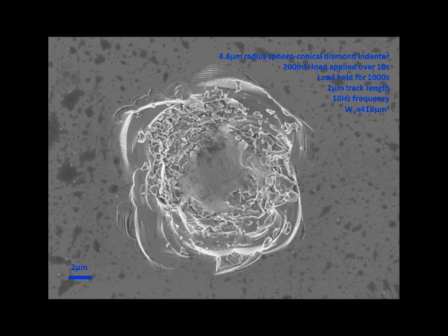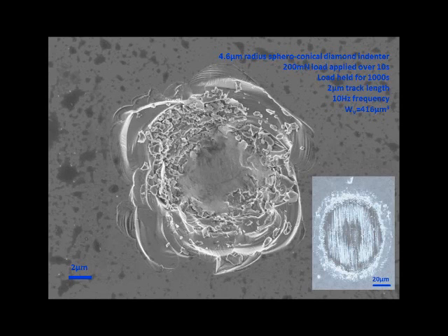Finally, third image showing wear scar under 200 millinewtons load. So some excessive silicon damage observed here, lots of cracking, lots of debris, and order of magnitude really larger than in the previous case at 416 cubic microns.